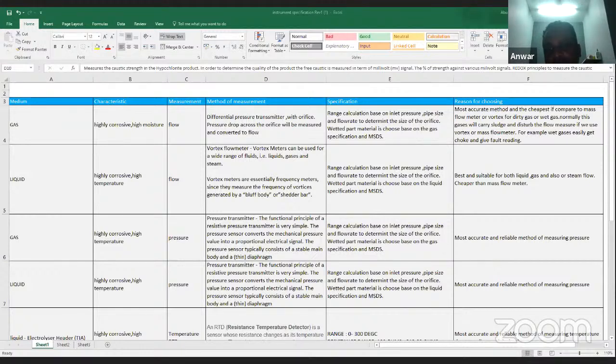And other requirements such as COD and also BOD, which we know in our process are not going to change so much, because there is no biological impact matter, as this is an inorganic chemical in our stream. So it will not change much. Normally for that kind of measurement, we take it weekly and send it to a third-party lab for monitoring purposes.